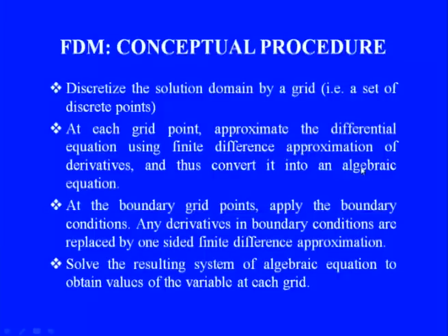Next step, what do we do? Collect the algebraic equations obtained at the interior nodes as well as boundary nodes to form a system of algebraic equations which will usually be sparse, and we just need to solve this resulting algebraic system to find out the values of the problem variable at each grid point.